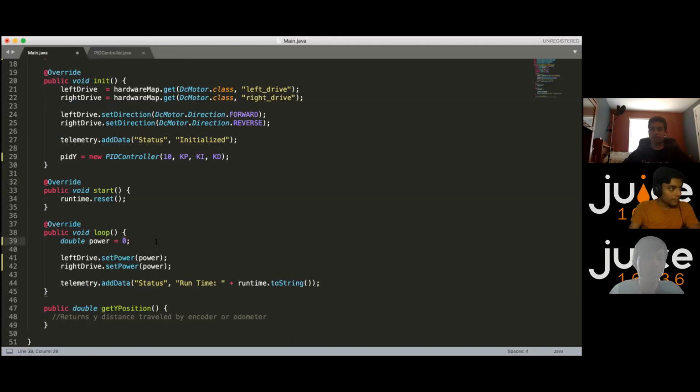Normally you can find those numbers wherever you bought your motors or encoders or odometer encoders, and it'll show something like encoder value per revolution. For ours it was 2048, so if you divide by 2048, you'll be able to calculate how far you moved with some constant.